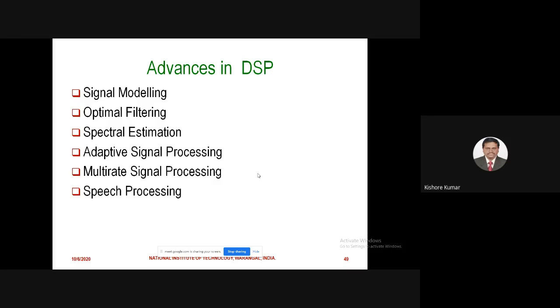Basically, in speech enhancement, I'll tell the basic idea: spectral subtraction, as you said. Spectral subtraction is actually the fundamental approach. There, what we'll do is try to calculate the energy by using the fast Fourier transform. We can estimate the signal energy and noise, and we will try to subtract. From the signal, whatever noise you have estimated, we will subtract the noise, and then we will get a signal. That is spectral subtraction.